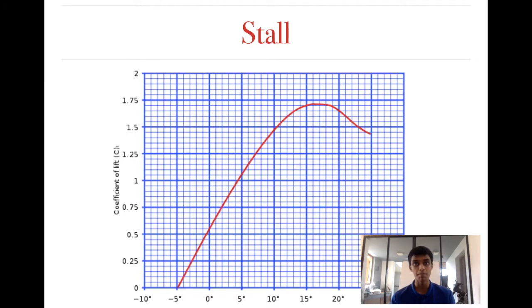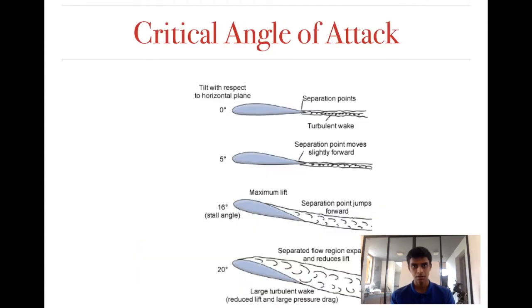You can ask me that question. But basically it varies according to the plane and also according to the Reynolds number. So we'll discuss that later. But basically the idea you need to get is that when the angle of attack increases beyond a certain point, a stall will occur. Now, there are two types of stalls, a high speed stall and a low speed stall, but this is called a low speed stall, okay? We'll talk about the other part later.